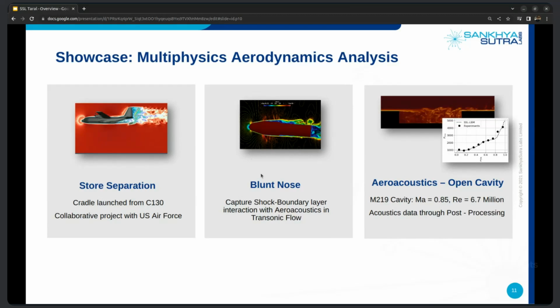And we've also done a few simulations on transonic flows, where the one you see in the middle here is flow past the head of a missile. So you see that we're able to capture the shock quite well that's forming at the nose cone, and even the interaction of the boundary layer with this shock and subsequent detachment of it from the surface of the missile as well.